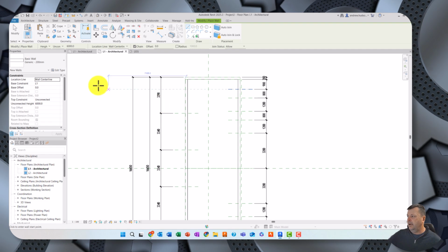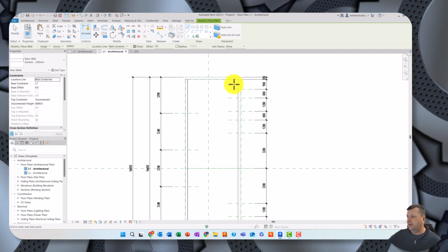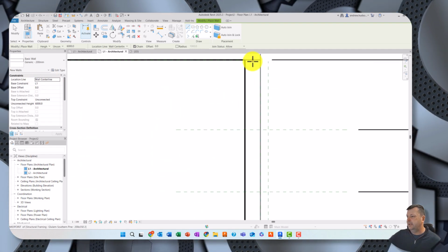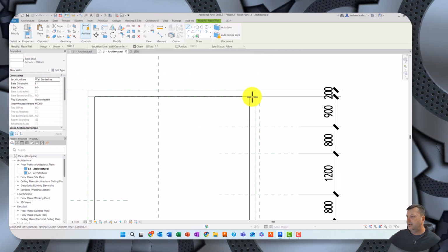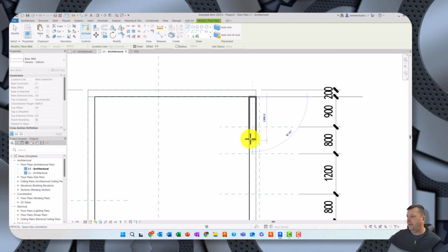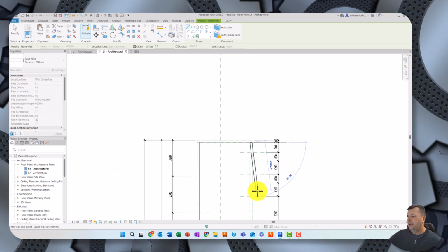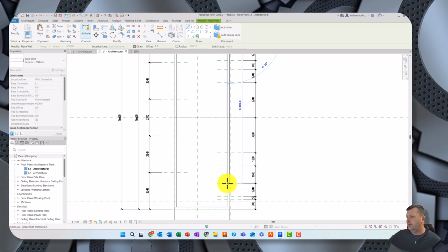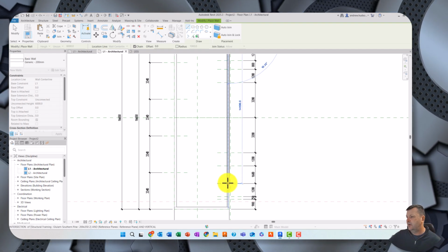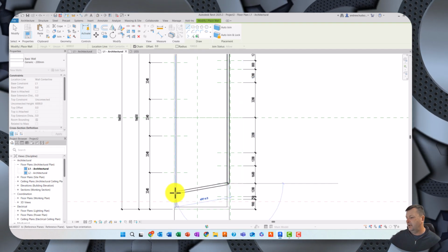So click on that. We are looking at the wall center line. What it's going to do, if we zoom in, is place our wall in the middle where that blue line is, so it's on the center of the beams. We want to go from that endpoint there, and we're going to drag it all the way down to, I think, that point there. If it's not, we can shift it.